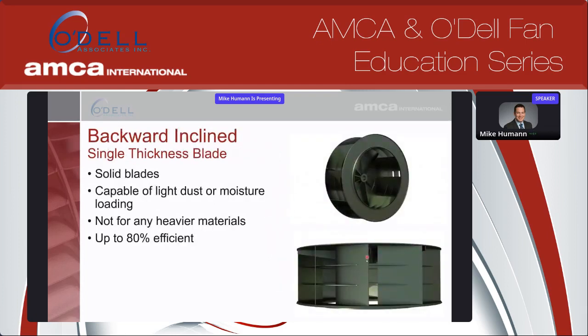Show you kind of the wheel design here. This is a single thickness blade. You'll see we have one single blade here. It's a kind of a backward cant on it. And as this rotates, we actually rotate this again in the counterclockwise direction. You'll see some reinforcements here just for support and to restrict any deflection in the blade.